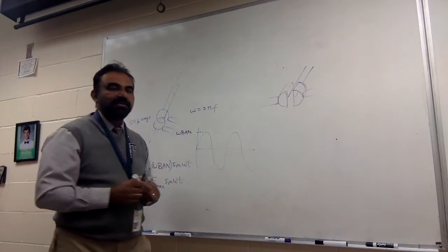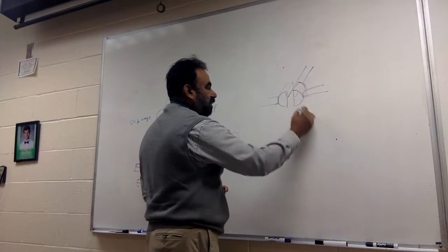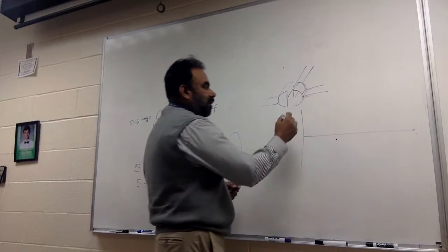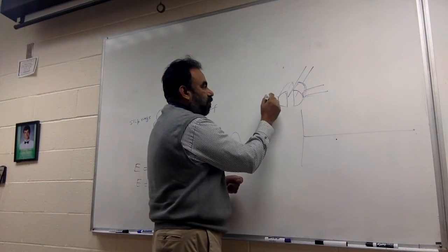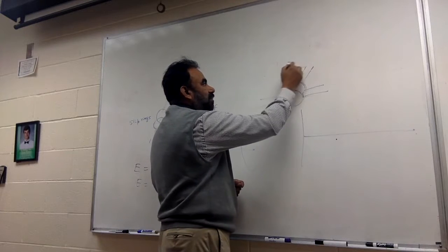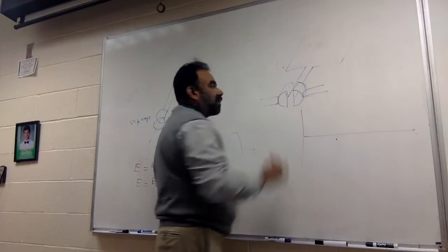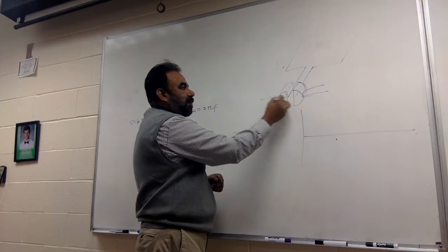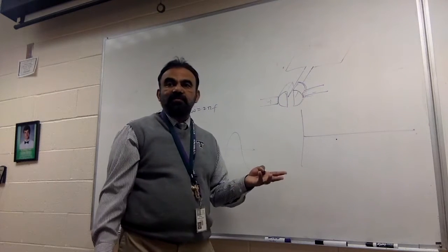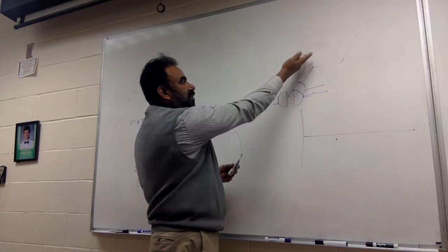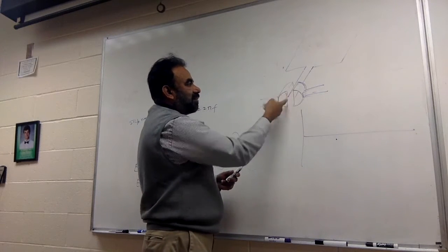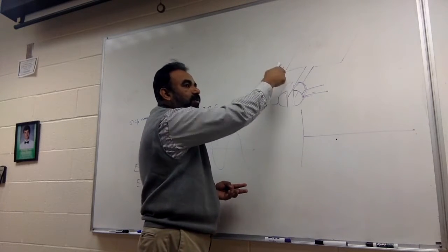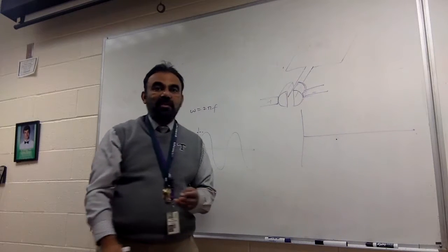And so what will be the consequence of this? The output that's going to come out will be, whichever wire comes on this side is going to push the voltage from here. So this will be positive and that will be negative at all times. Because when this flips, the commutators just exchange places. But still the conductor which is here is moving in one particular direction, therefore it induces the same polarity on this side.